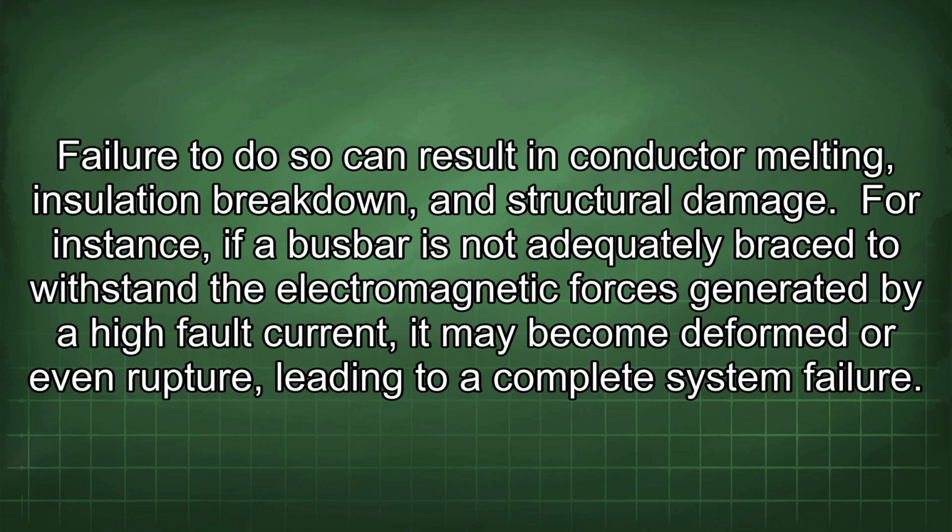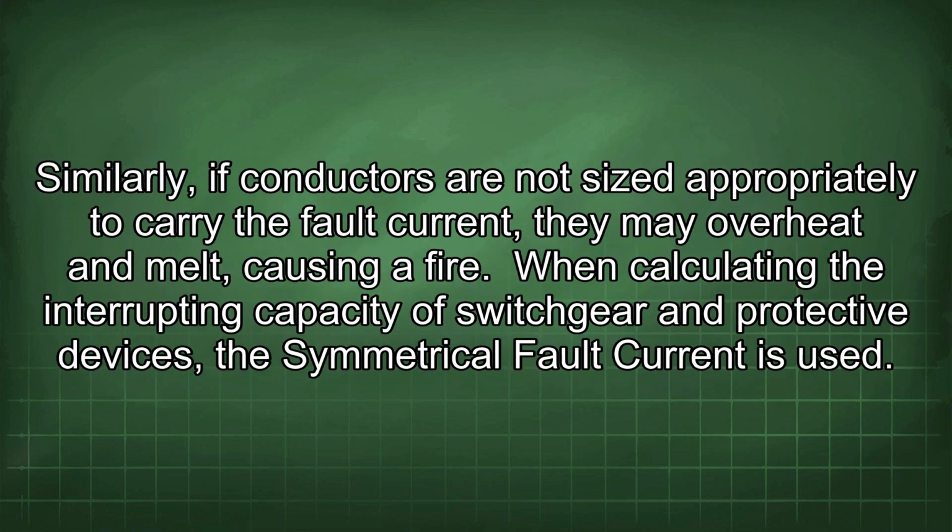For instance, if a busbar is not adequately braced to withstand the electromagnetic forces generated by a high fault current, it may become deformed or even rupture, leading to a complete system failure. Similarly, if conductors are not sized appropriately to carry the fault current, they may overheat and melt, causing a fire.